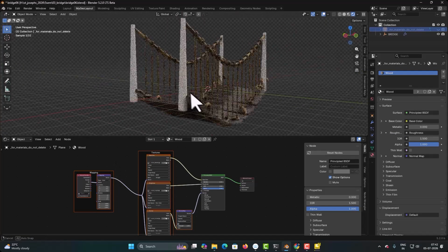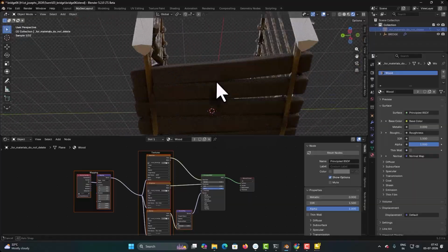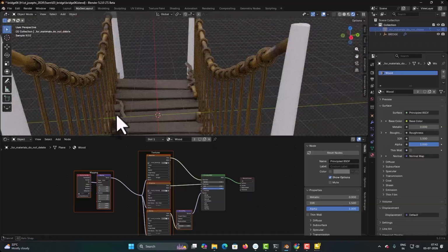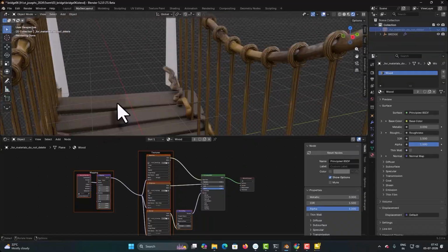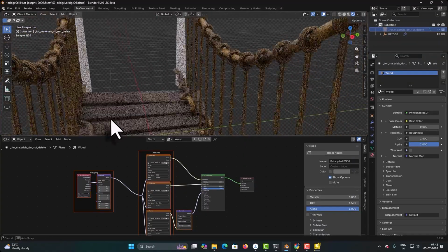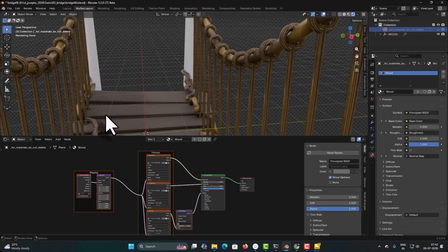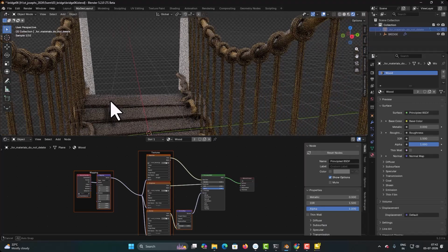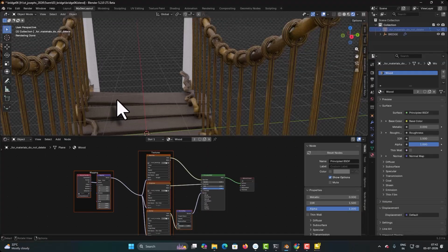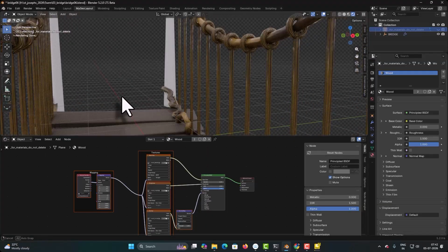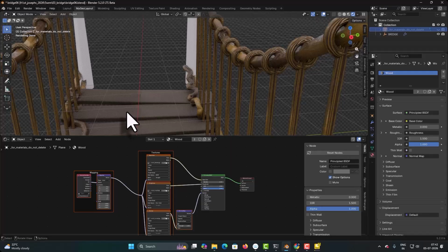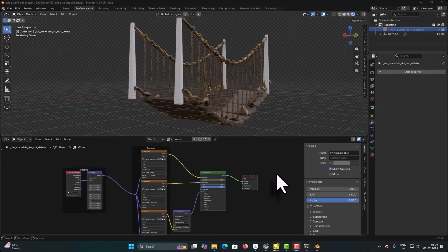I have added the material, but if you see, it is not correctly showing on my wooden plank. This is because we have created this mesh, and when we apply the material, if you already know the principles of how to apply the material, we have to unwrap its UV map. In case of models that we create manually, we can do it directly, but these models are created using nodes. We have to work out a way to unwrap and use the UV map. So we have a workaround for this, and the very first workaround we have to do in our node.